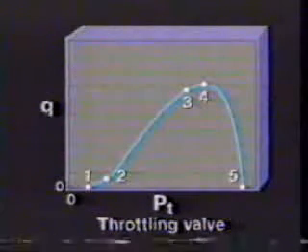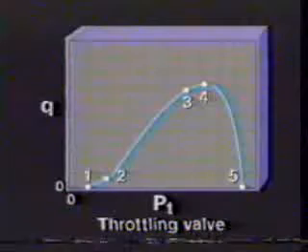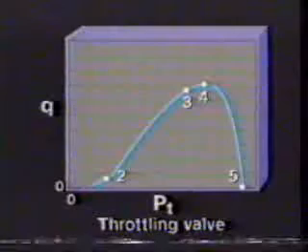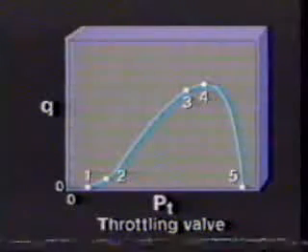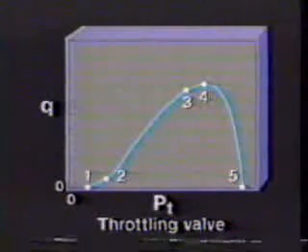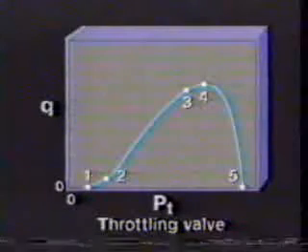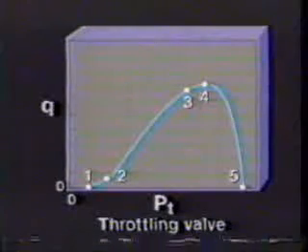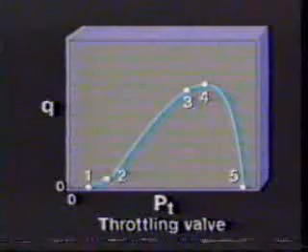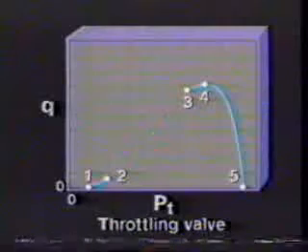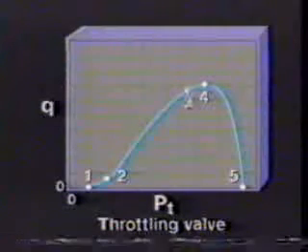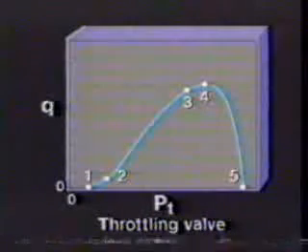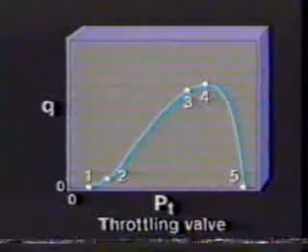The vertical axis is flow rate, and the horizontal axis is tubing pressure. At very low tubing pressure, to the left of point 1, the valve is closed. As the tubing pressure reaches point 1, the valve begins to open and gas flows from the casing to the tubing. The flow rate increases as the port continues to open. Throttling occurs from point 2 to point 3, at which point the port is fully opened and throttling ends. The maximum flow rate occurs at point 4.